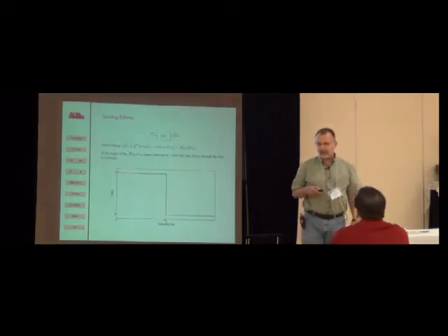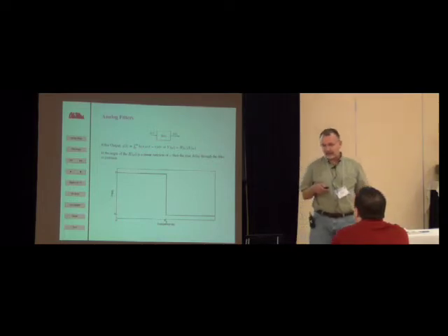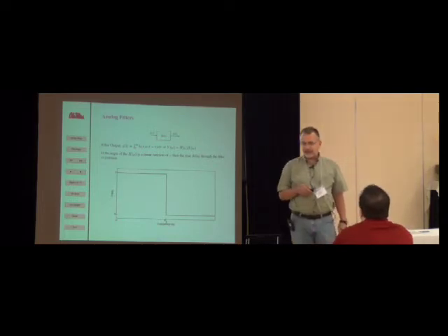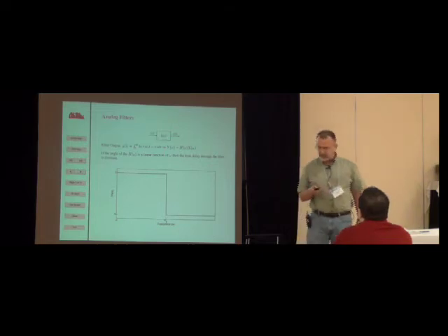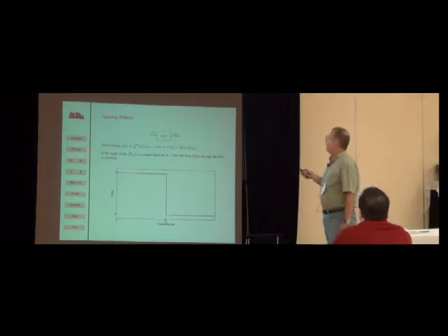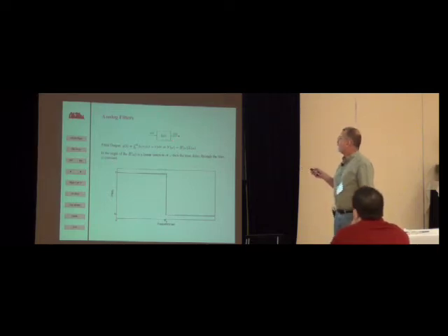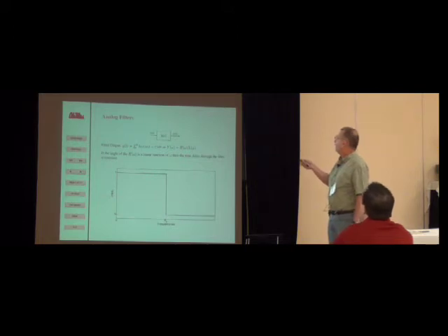So a little bit about analog filters before I talk about digital filters. An analog filter is just a linear time invariant system. And you can represent it this way, where x of t is your input, y of t is your output. And if it's a linear time invariant system, you can represent it with an impulse response h of t. And in the time domain, you can write the output, which is the convolution of the impulse response and the input. I started this at 0 because I assume I have a causal filter. For a non-causal filter, you just start at the lower limit at minus infinity.